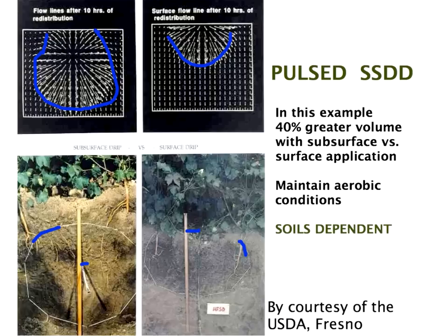Now, this is perfect Central Valley, California soil. We don't get soil like this, but the principle still applies. By this pulsing action, we get a much larger wetted volume, so where there isn't water, there's air. And where there's air, we're getting aerobic treatment of the anaerobic bacteria coming through with the effluent. And obviously this will be superior to this, which is more saturated.